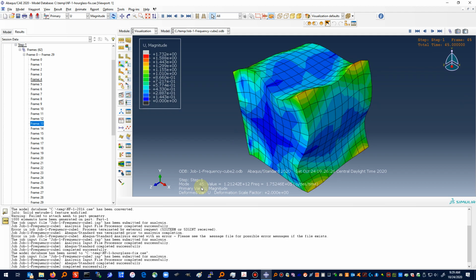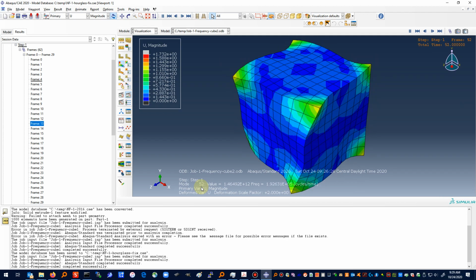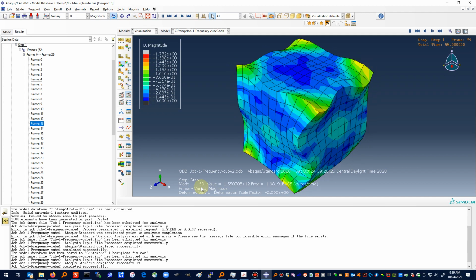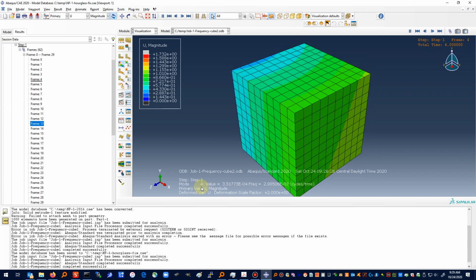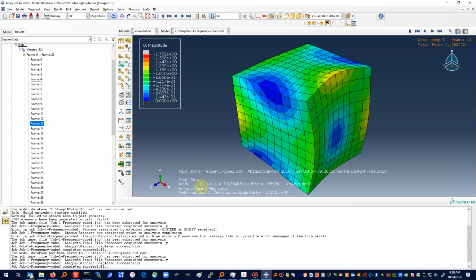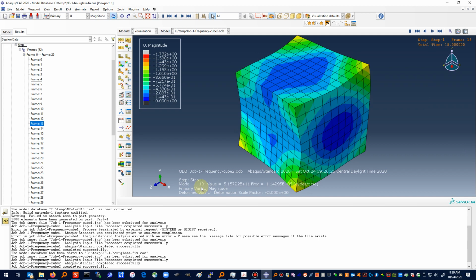You know, you may ask, well, how can you ever have anything that's free? Well, you can actually test something. Oh, there's some spurious modes. You can actually test things in a situation that approximates free. So you can take a slender bar or this cube and hang it by a very thin wire.